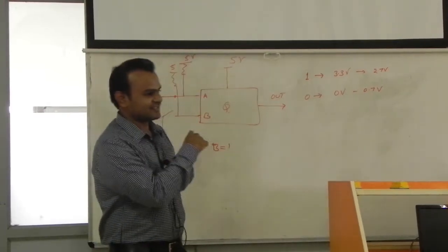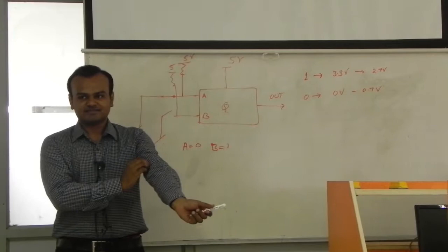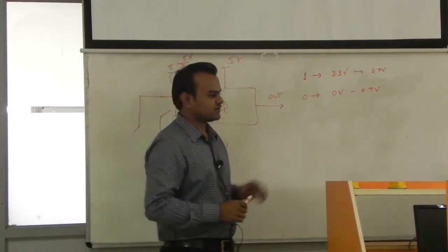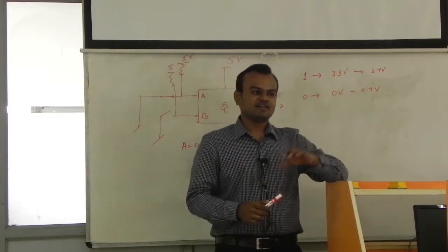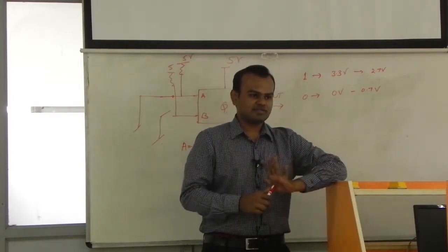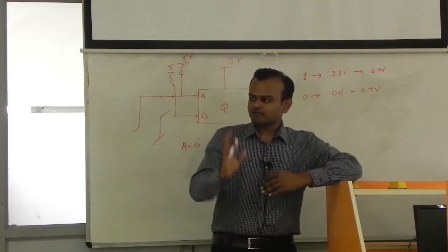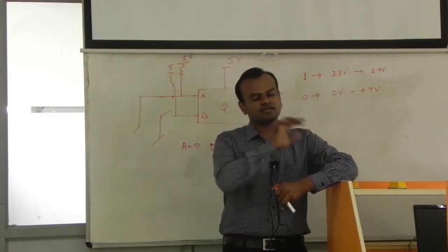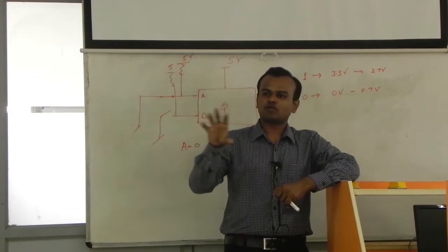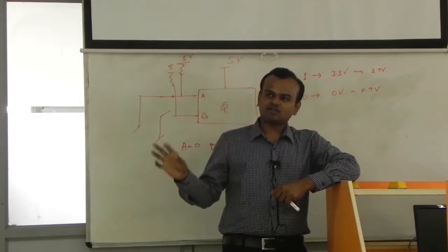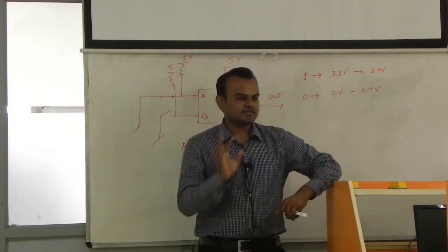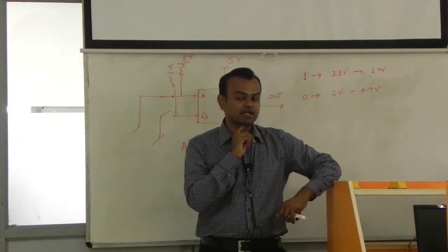Now in an advanced microcontroller like this, you don't connect an external oscillator or external crystal. Internally there is an oscillator present which can give you different kinds of frequencies. Usually one of them is a main clock which will power each and every peripheral core of the system. That clock in this particular microcontroller is set as 12 megahertz.